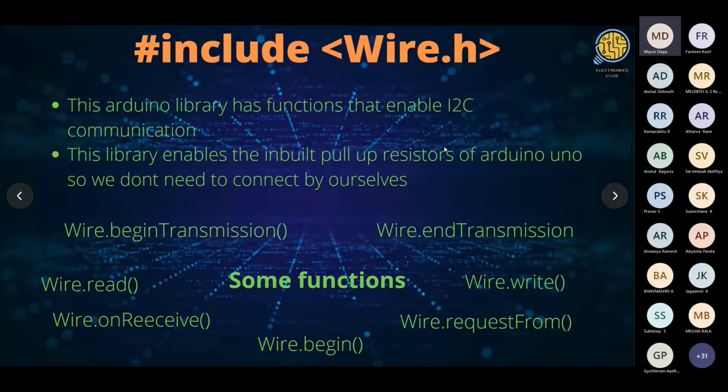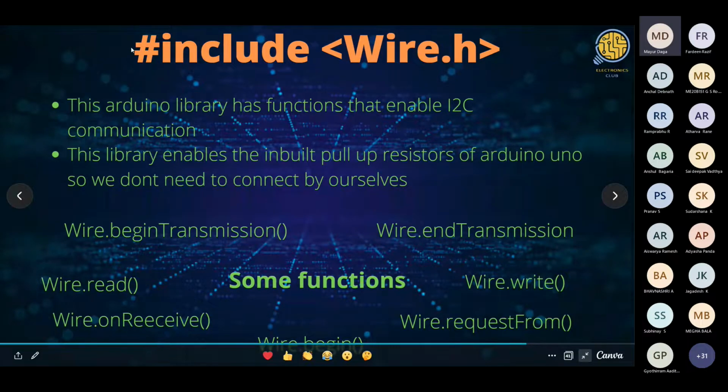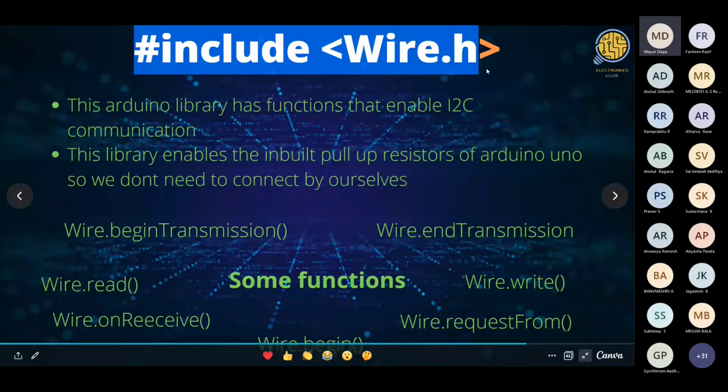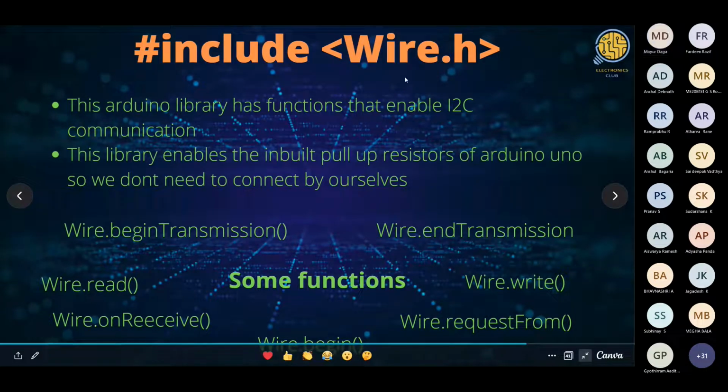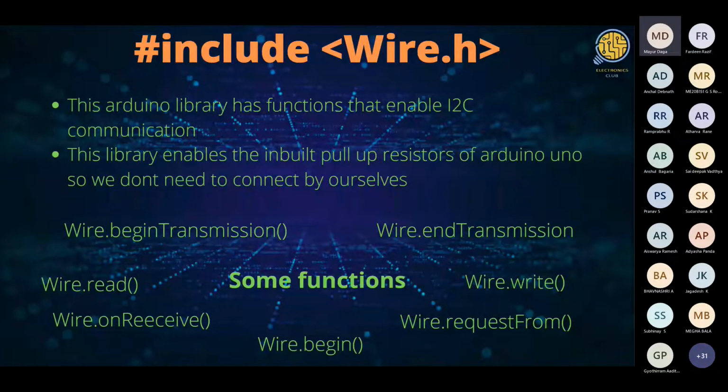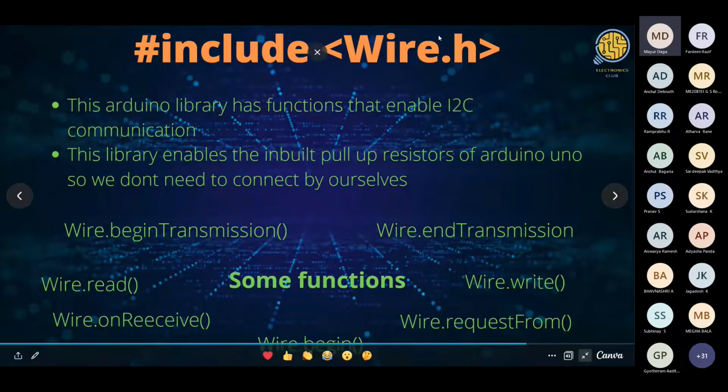Now, while coding in Tinkercad, we will need the #include Wire.h library to start communication between master and slave with the I2C communication protocol.